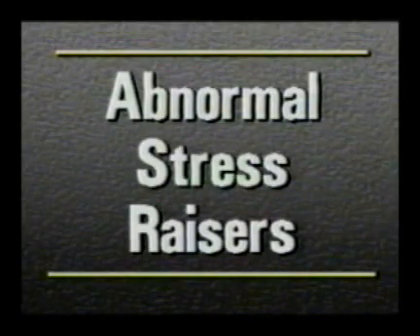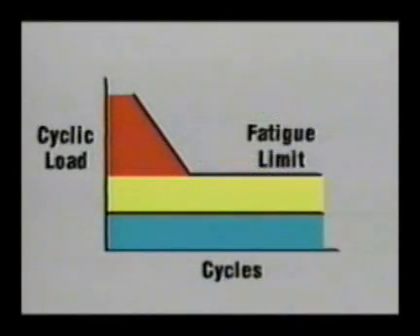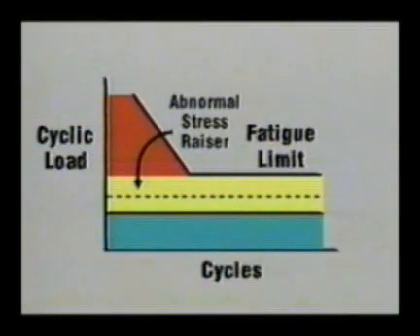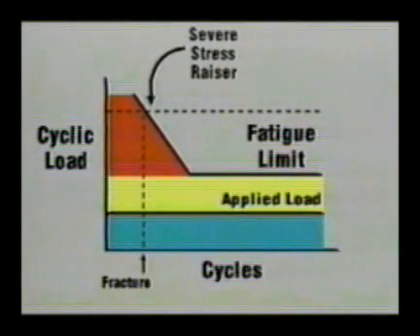Earlier in the course, you learned about stress raisers, what they are and how they are created. Normal stress raisers, such as material flaws, holes, and fillets, are usually not a problem because they're taken into account by designers. Some abnormal stress raisers can be tolerated in parts since there is a safety factor. Severe abnormal stress raisers multiply the effect of normal cyclic loads above the fatigue limit, which can lead to fracture.